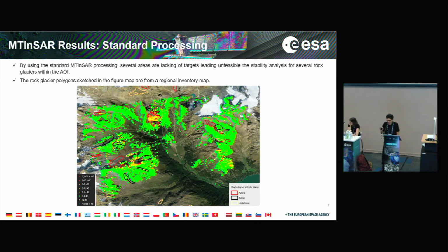First of all, we eliminate the images, and so the interferograms, where we have snow cover, according to our preliminary investigation of the coherence evolution in time. Moreover, we try to at least partially overcome the problem of phase aliasing by forcing the algorithm to search for higher velocity. Basically, we iteratively used the velocity estimator not centered on zero velocity, but moving to higher velocity values.